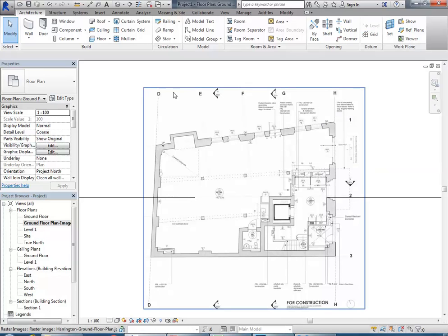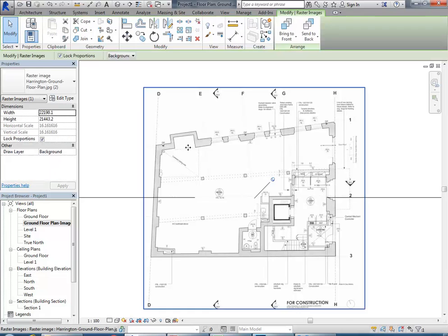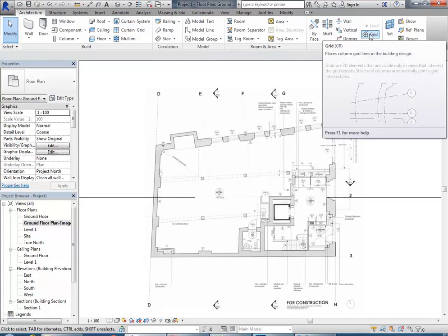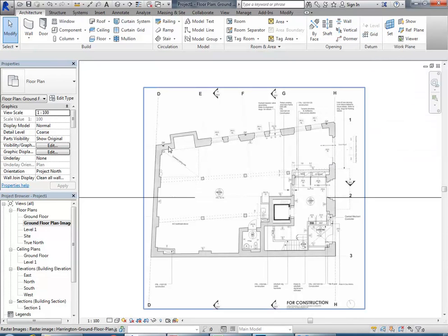Well, it often depends on the scale of the building. So grids tend to be used mainly for larger buildings, but also when you have a column grid, like we do here. So we've got a column grid, but you can see here the person doing this drawing has also used a grid for the external walls, which is standard, that people do that usually.